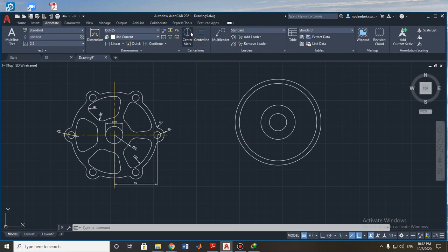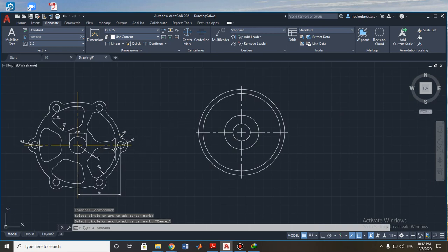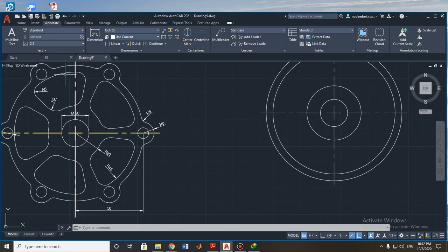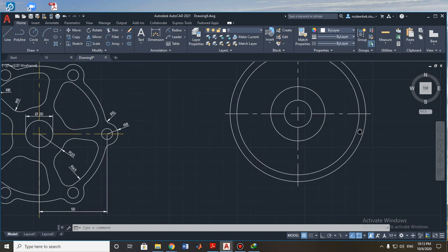First of all, I want to put a center mark here to see our drawing very easily. So I want to build the left small circle, the right small circle, and then I want to use maybe the mirror tool, maybe the array tool to copy it 6 times. So as we know, the center of these circles is located on the line of this circle. No, sorry, the big circle, which is 50 millimeters radius. So excuse me for my mistake.